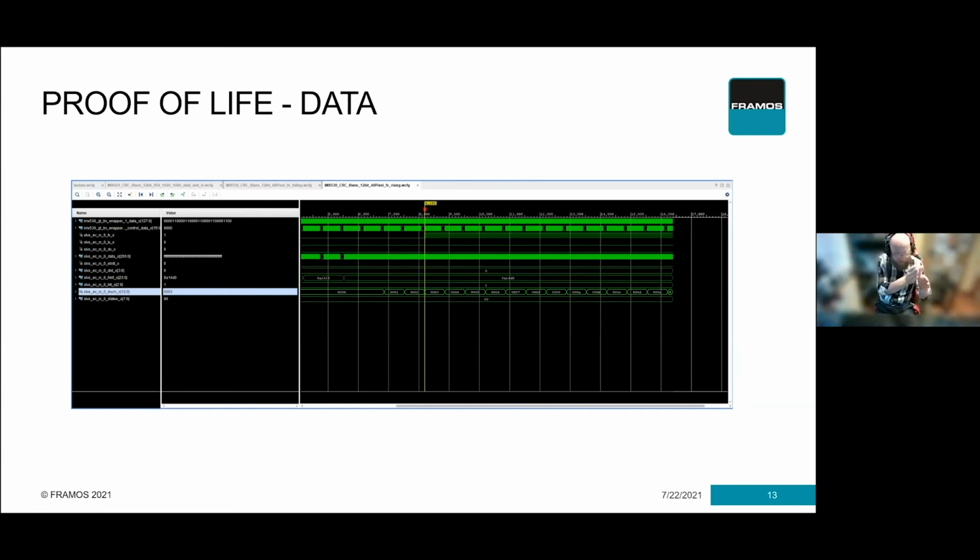But if you can validate the steps as you go through your design, that's the key to it. I have to say that we use ILAs and internal grabbing much more often than we use oscilloscopes. So, for example, in this office, I think I have a 250 meg scope and a logic analyzer. Okay. Which is something like SLVS at 4.5 gigabits. This isn't going to work. Hence, we look at it in this format.